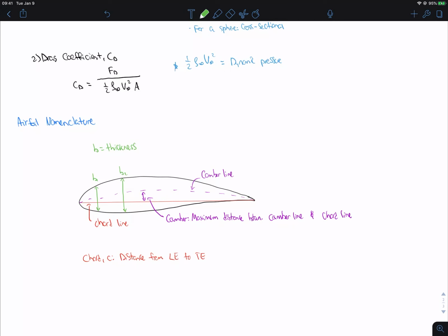We're doing a very similar thing here, but instead of using a pitot tube, we have a pitot-static tube. This static port is included on this pitot tube. Once we use this, again, we're going to find the stagnation pressure and the static pressure, and then we can find our local airspeed in the system.